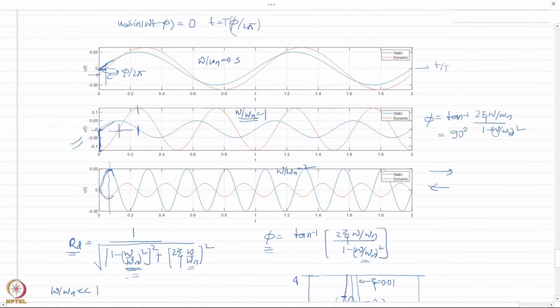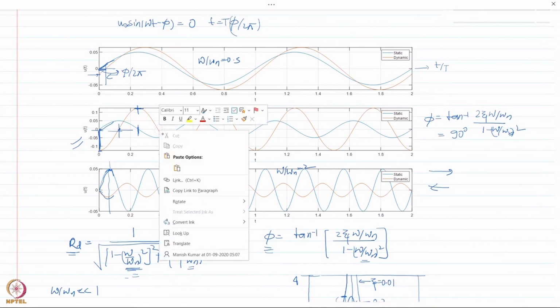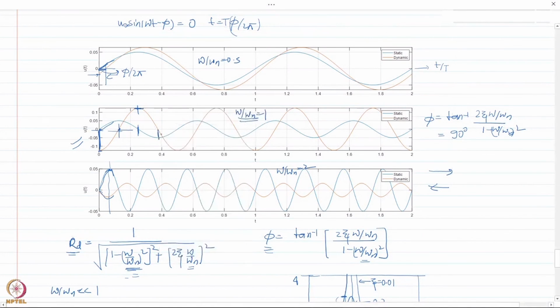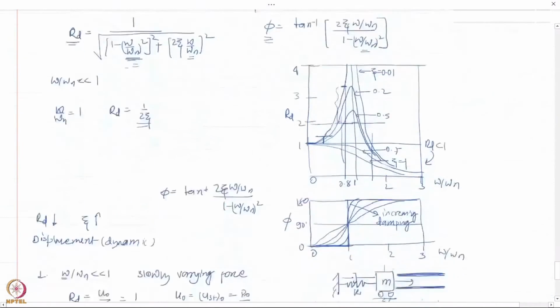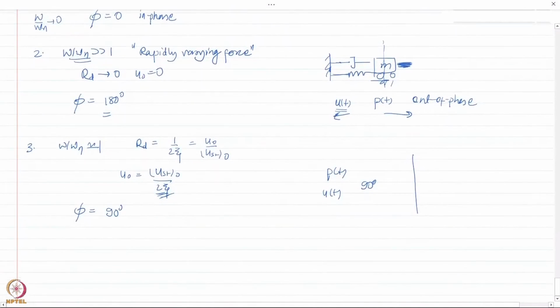When it starts at 0, it is minus 90. When it reaches the positive amplitude, then it goes to 0. And when it goes to 0, then you have the maximum value of the response. So those are shifted by 90 degrees. These are the typical scenarios. Of course, loading won't always be at these extremes. It would always fall in between, or closer to one of these scenarios. But based on these three, you would be able to interpret or predict somewhat the behavior of the dynamic system.